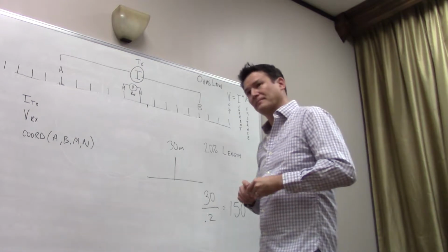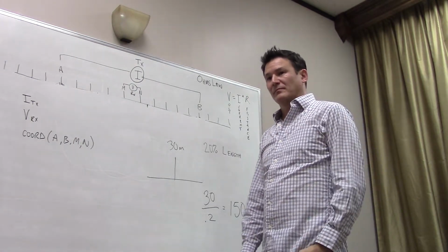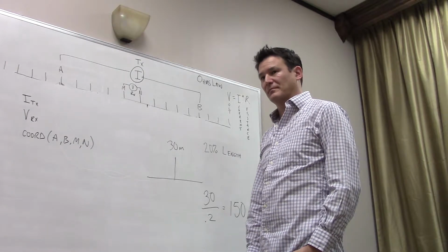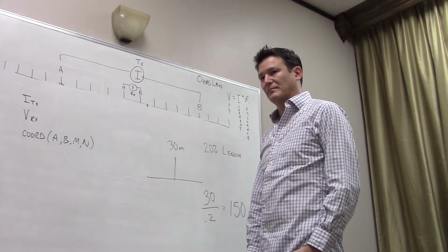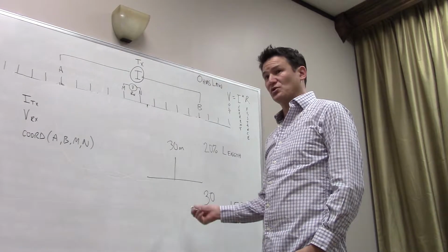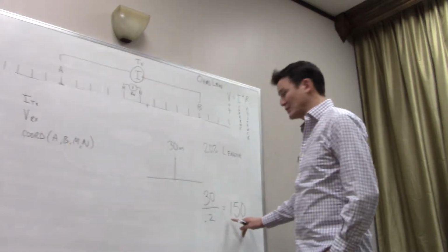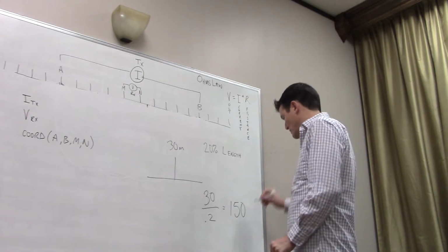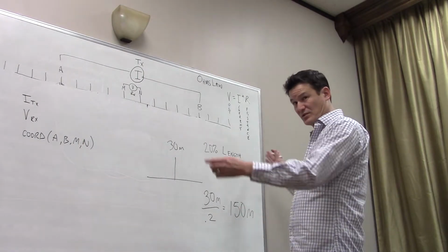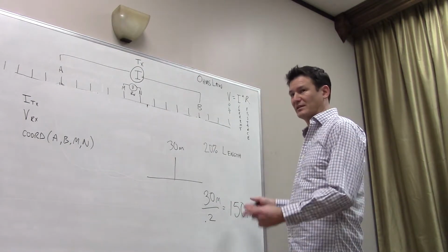Want to interrupt you here, just to get it through. If we're going 30 meters in depth, we're only going to see 20%, or the resolution would be 20% of 30 meters, right? No, the resolution has to do with the electrode spacing. So if I decide that I have to spread out my sensors at least 150 meters on the surface to reach 30 meters, how many electrodes do I want to put within that 150 meters?